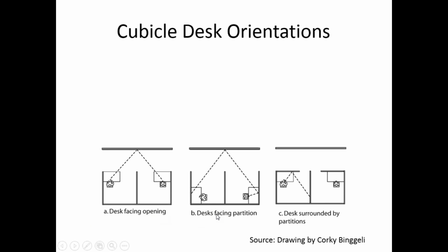Desk-facing opening and desk-facing partition. So, thinking about the orientation of a worker within a space: if you have a large, expansive hall, it's just this big, flat area for sound to bounce off of, so you might want to change the direction that they're facing. Here it's bouncing off of them. Here it's bouncing from one person to the other.